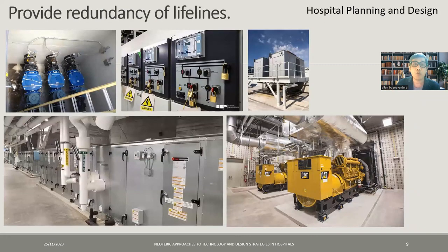Hospitals are expected to provide safe and reliable healthcare to patients. Planning not to fail is the goal of designing utility systems. Redundancy in lifeline systems includes mechanical, electrical, which is emergency and normal power, domestic and hot and cold water that can be used for at least 3 days, a plumbing system that will not fail, technological systems, which is redundancy of